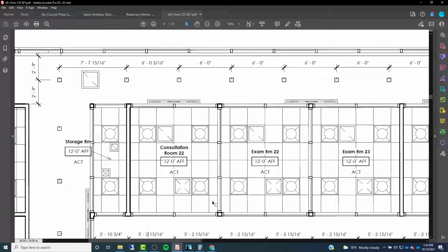And what I need to do is basically just center out these 4 ceiling tiles, and then I'm going to have a half tile on either side. Okay, so they're going to look at that, and that's going to give them all the information they need to build the ceiling grid in. Once they built the grid in, they just have to look at which tile the things go into. So in this example, these light fixtures are going to be placed in these 4 areas, right? So you're going to have a total of 4 of them, and you're just going to look at the grid where those need to go.